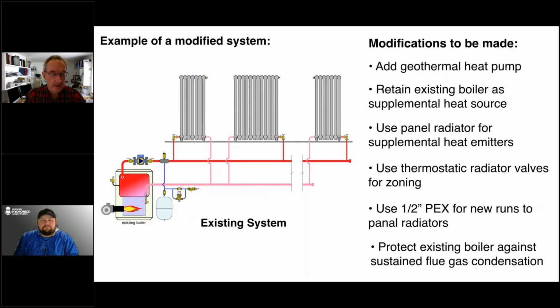And again, on your AV unit, as you've explained to me, you can either draw the heat for defrost from the electric backup, or you could draw it from the Turbomax tank. So that's one of the nice advantages, honestly, with air to water compared to air, is that the thermal mass that's available in a hydronic system is typically enough that you can draw the heat you need for defrost without affecting the interior comfort.